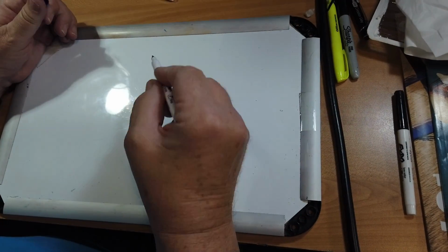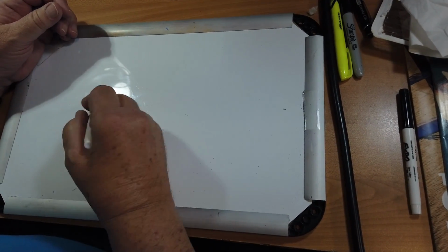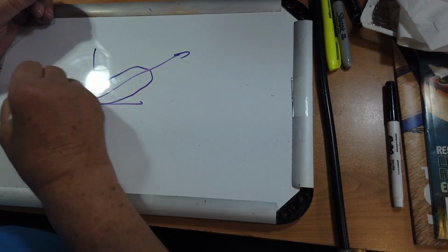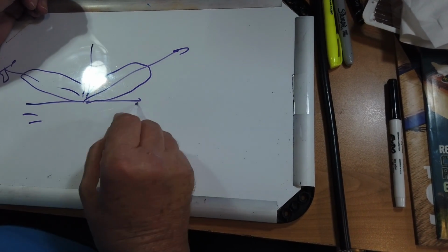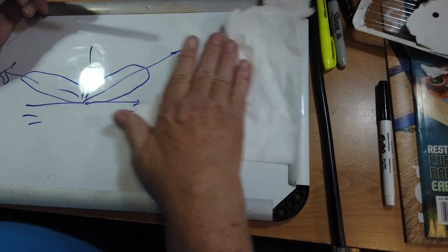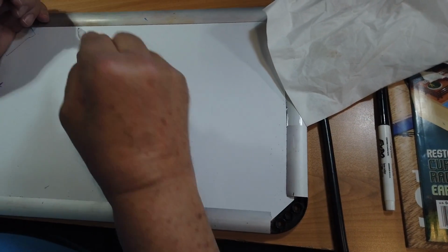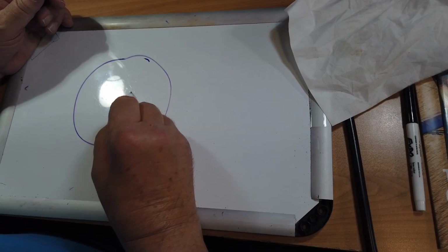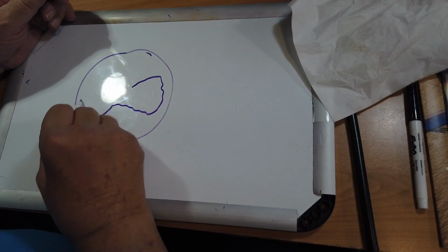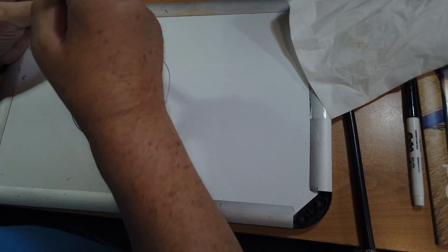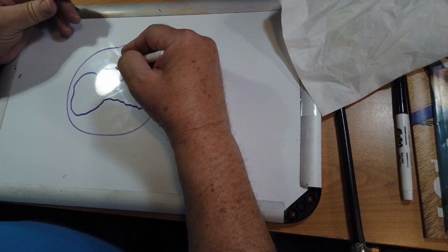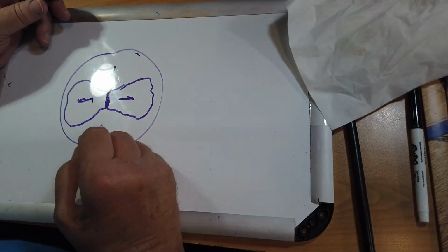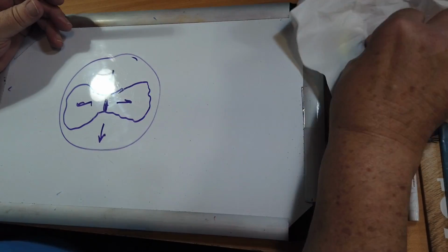You can get a 3D pattern if you want, but they're hard to see. But if you look at this on the horizontal edge, you get an elevation angle that comes out of here, because ground is important. And if you look at it from the top, here's a circle, and you might get something that's broad here, a little less here. That's looking down at the top of the pattern for a dipole. You can see that if the dipole is this way, it tends more toward broadside than it does out the edges.